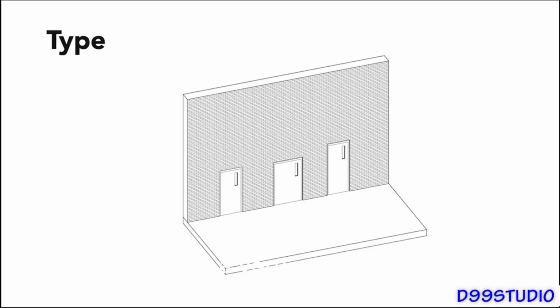A very common variation might include the size of the door. So maybe we have a standard size, maybe we have a wide one, maybe we have a tall one. We could even have ones that have the actual numerical descriptions in the name. The overall configuration in all these cases would remain the same and be constant and driven by the family, but those specific widths and heights would vary with the type.